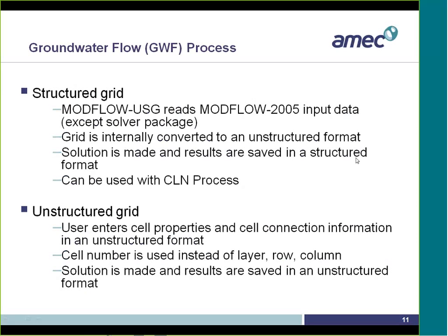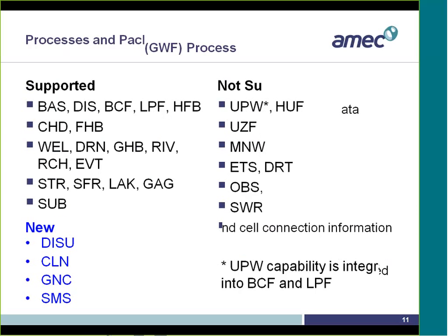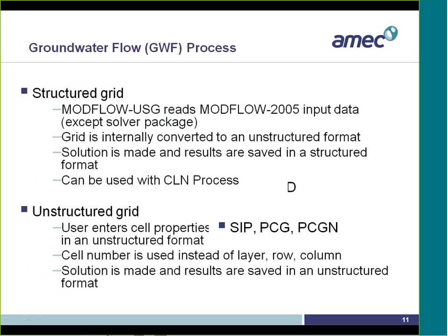So essentially, if you have MODFLOW 2005 data sets, with the packages that are supported, you should be able to run it right away within MODFLOW-USG just by switching to the MODFLOW-USG solvers. And also you should be able to read back the binary files that are generated just with your regular MODFLOW 2005 binary file readers.